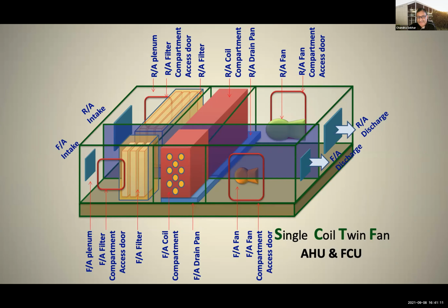And what that does is it allows you to accomplish what we call demand ventilation in individual occupied zones. So if you have a central system, you can actually manage your individual zone requirements depending on what you need, because you now really have two air streams that you can manage with.